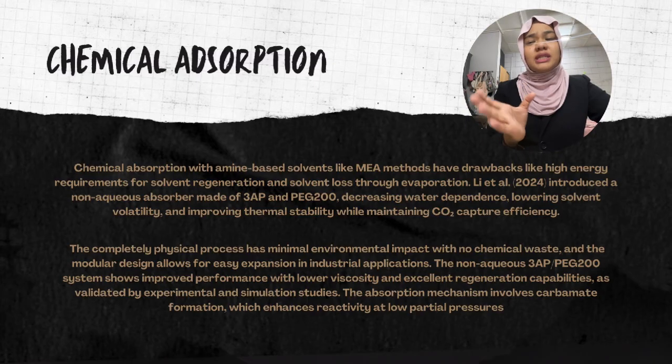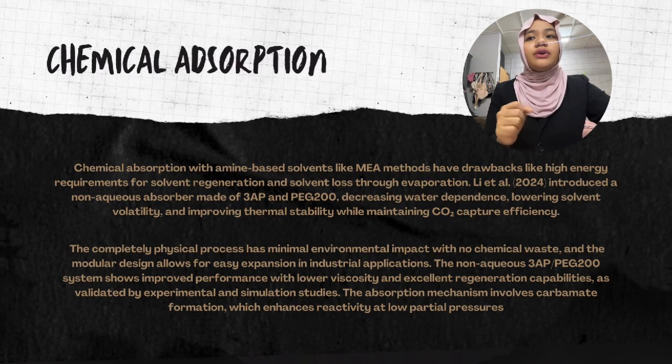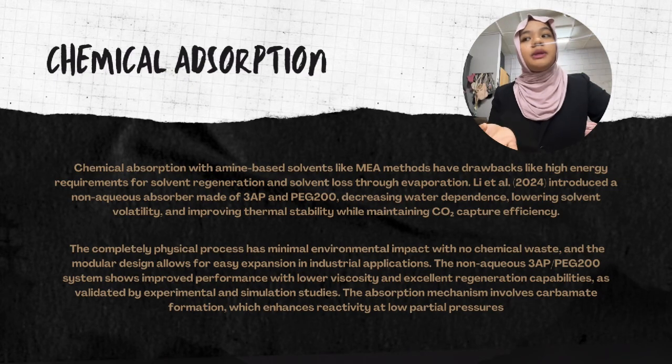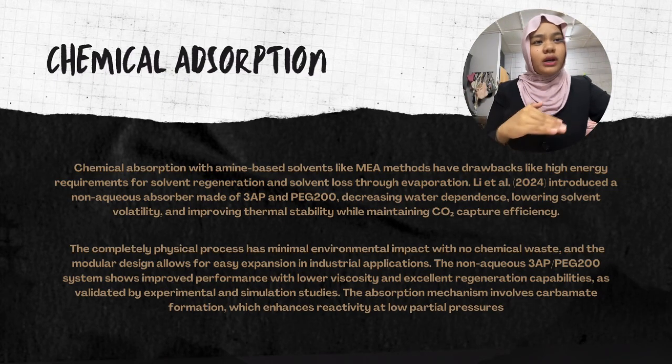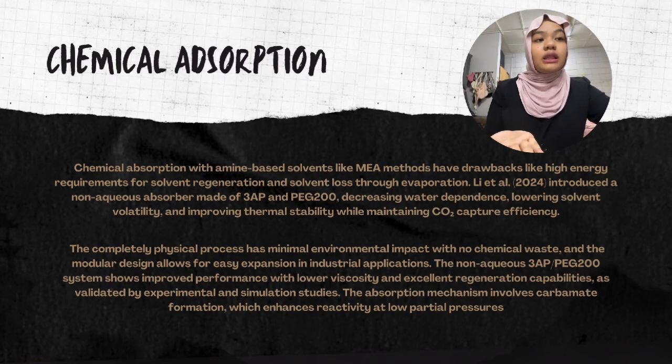The completely physical process has minimal environmental impact, which is good because there is no chemical waste, and the modular design allows for very easy expansion in industrial applications. The non-aqueous 3AP or PEG200 system shows improved performance with lower viscosity, but also excellent regeneration capabilities. These are validated by experiment and simulation studies, where the absorption mechanism involves carbamate formation, which enhances the reactivity at low partial pressure.